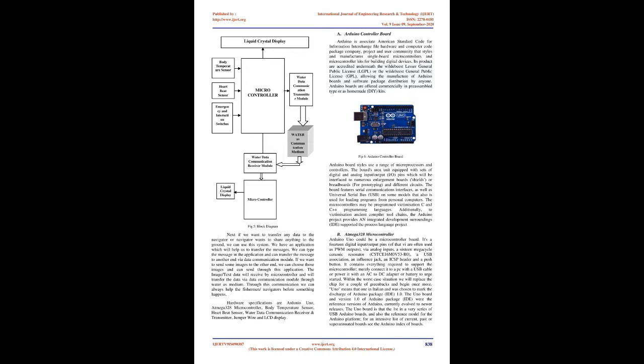System model. As shown in the block diagram below, our system comprises a couple of microcontrollers, heartbeat sensor, temperature sensor, and data communication module. We divided the system into two parts, transmitter module and receiver module. In the transmitter end, we have a microcontroller, LCD display, heartbeat sensor, temperature sensor, and data communication module. Then the receiver module consists of microcontroller, LCD display, and data communication receiver module.